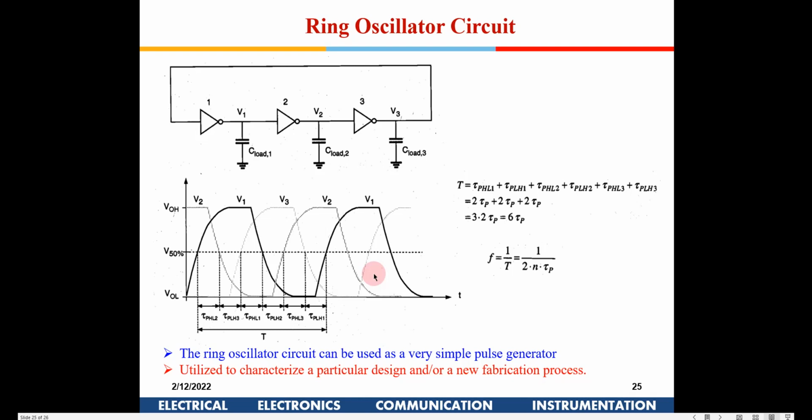So this is basically the delay of these inverters. This is a figure of merit for this particular set of devices, for this technology device. There will be many parameters, like VTH and body bias, but for a VLSI designer not very keen on physics, those parameters are not very important. This is the key performance result for me, because it gives the total delay of the back-to-back inverters.